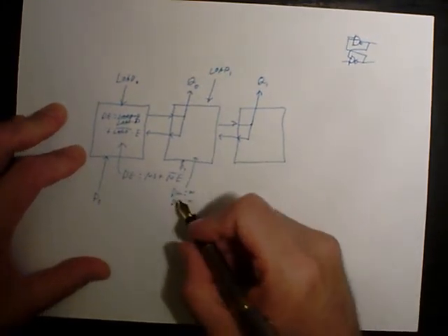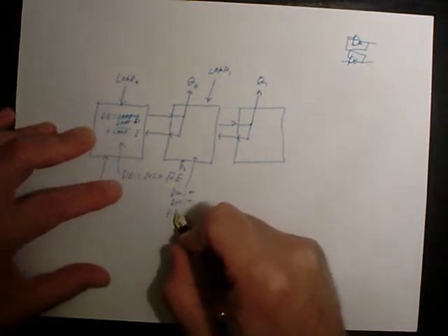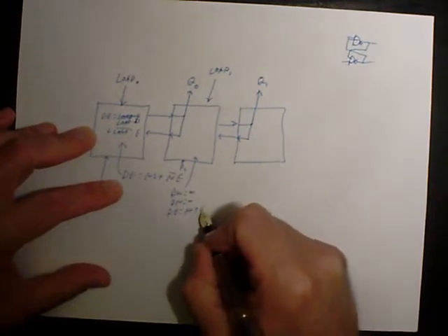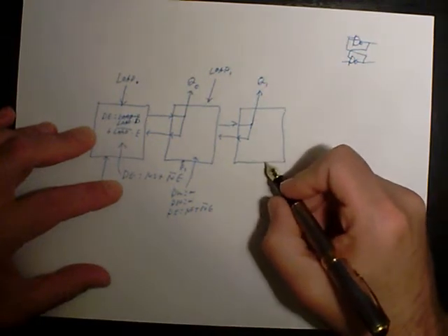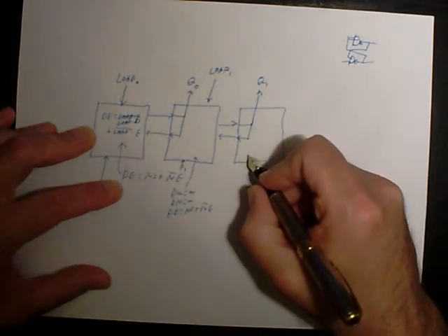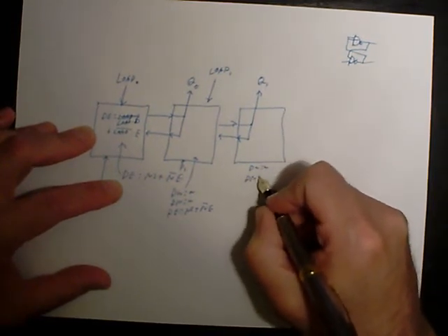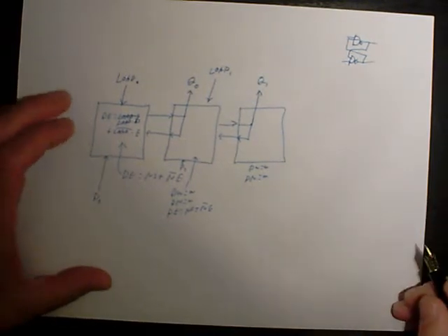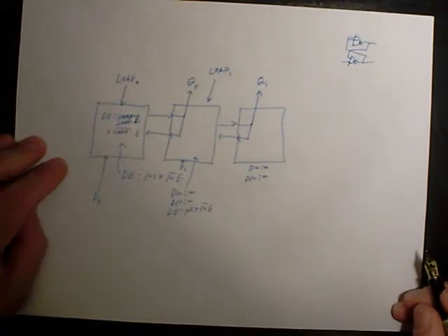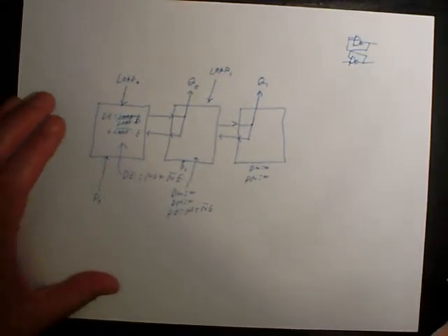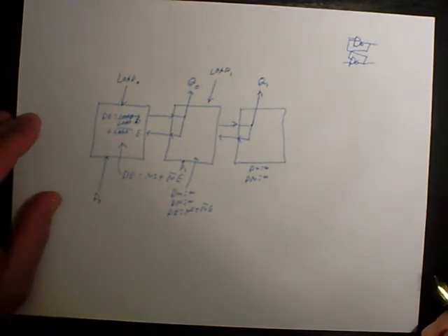And we can put the same equations in here. Instead of just data west equals west and data north equals west, we can also add data east equals north-south or north bar east. And then in this cell, we can have the equations data west equals west, data north equals west. And so now we have 3 cells implementing 2 bits worth of D latches, and this asymptotically comes out to be 1 cell per bit. So if we have 100 bits, we can implement it with 101 cells.